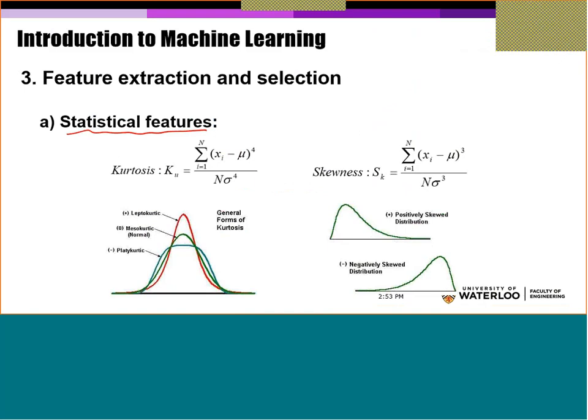What are statistical features? For example, you are measuring the peak of a partial discharge, a value, a number. So you will have a lot of data, 1, 2, 3, etc. You take all of this data and you draw its distribution. So you will have an average, you have standard deviation values. These are all statistical features: the average, the mean value, the standard deviation, the kurtosis of the data. The kurtosis is how sharp or how wide your information is.